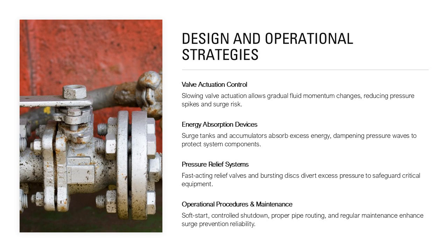Industry standards such as API guidelines recommend specific practices for surge control, including valve sizing and actuation timing. Regular maintenance and inspection of surge control devices ensure continued effectiveness. By integrating these preventive measures, engineers can significantly reduce the risk of surge-induced failures and enhance system reliability.